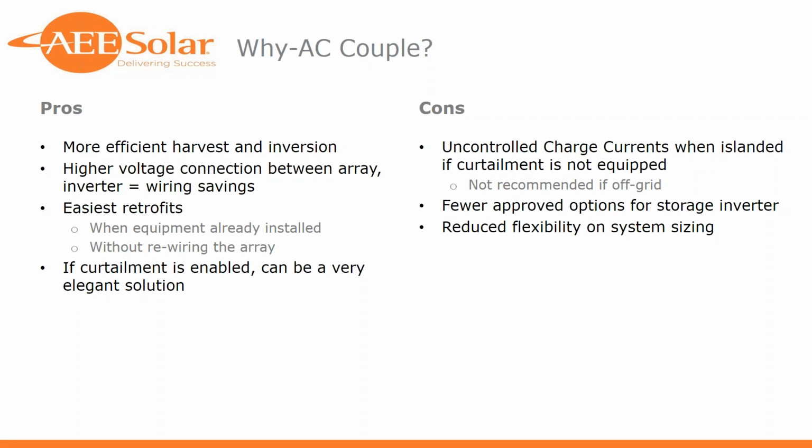That's an example where it goes back to my first point here on uncontrolled charge currents. Really small battery, great. I keep the PV inverter running. I keep producing power. When the grid's out, what happens when you turn the TV off, the refrigerator cycles off, there's no loads? The battery, that current's got to go somewhere. When you're using really small battery banks in an AC coupled solution with no grid, you're going to have a bad time.